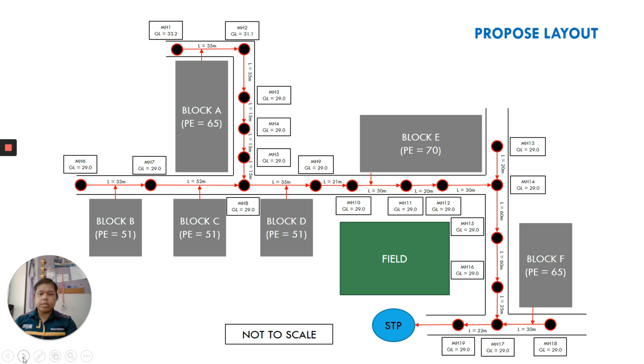distribute the sewerage line. So in my case here, I will start our manhole here, and then you have to put your ground level here. In order for us to know your ground level, so we can calculate or determine what will be the invert level for that manhole. So we have to know the connection of each manhole from the first one until the discharge point.